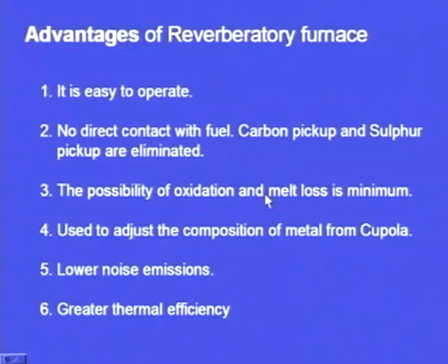So there is no direct contact between the fuel and the charge. So carbon pickup and the sulfur pickup, which are arising in the case of the cupola furnace, are eliminated when we are melting the charge in a reverberatory furnace. The possibility of oxidation and melt loss is minimum.